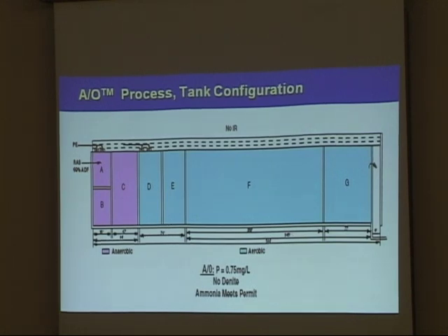All right? And this is the one that's going to help you get your phosphorus removal. As Paul said, you're getting 0.3 on your effluents. This is really good. You also get a well-settling sludge because of the anaerobic sludge. This type of sludge is a well-settling sludge typically.